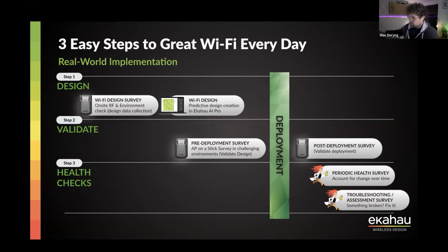You give it to the mounting cabling team. They put everything up, everything is working. And then the next step, a week or 2 weeks later, after you let it settle in a little bit, so your network is running optimal channels at optimal power levels, you've adjusted whatever you wanted to adjust, you go back to the site and do a post-deployment survey to make sure that the network operates exactly as it should be operating.